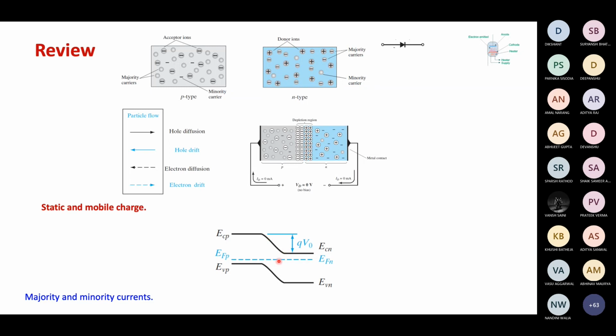And in this junction region, as you can see, if we see the distance between the Fermi level and the conduction band, and the Fermi level and the valence band, it is almost equidistant at the middle, which means that now both electrons and holes are actually less. So that's why this region is known as the depletion region. That is essentially the picture here.